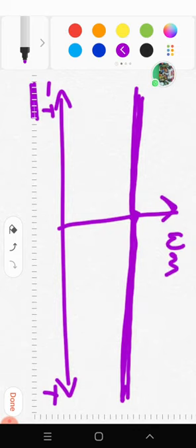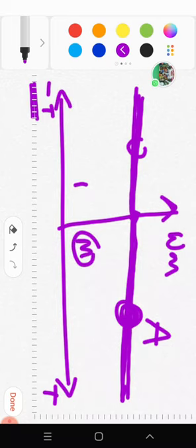So we can observe, if operating point, normal motoring point is here, suppose point A, normal operating point in motoring mode. We know the four quadrants. So this is a motoring quadrant, this is braking quadrant, and if we consider this speed as positive, then it is forward motoring and forward braking quadrants.